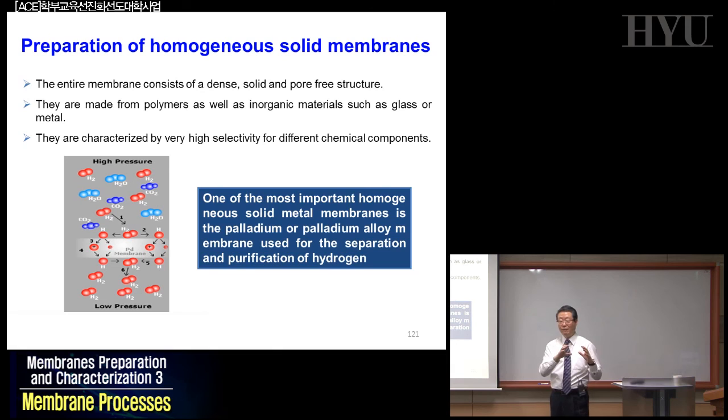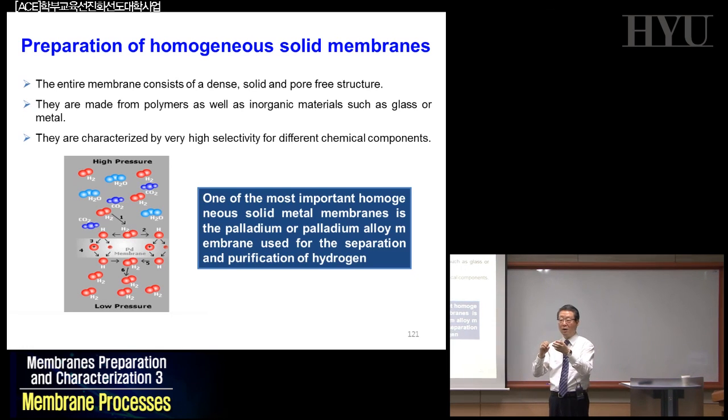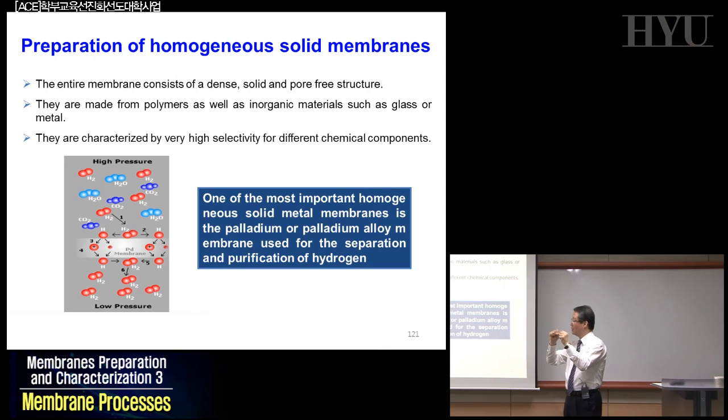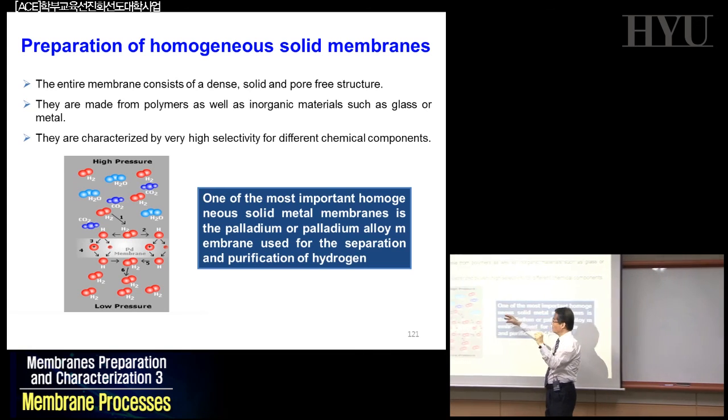But if you have coals and heat them up with a catalyst, and generate hydrogen and CO2 or CO, this is what they call the syngas process, at high temperature and high pressure, usually over 300 degrees C and 20 bar, you generate hydrogen and CO or CO2, so this is the feed mixture here.